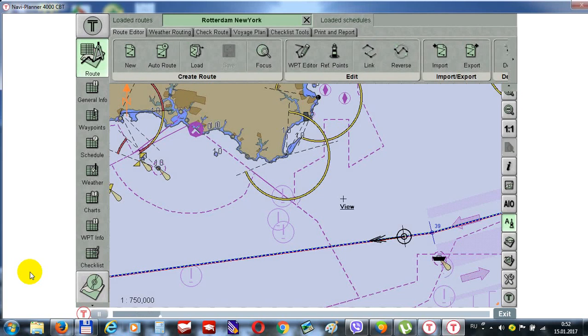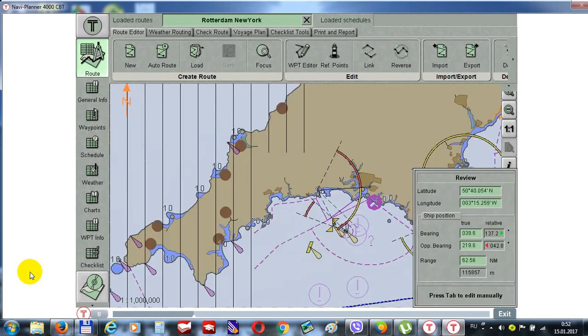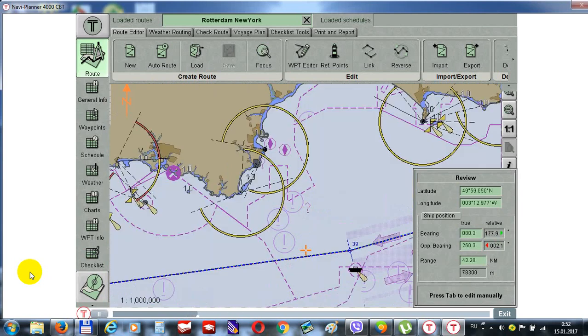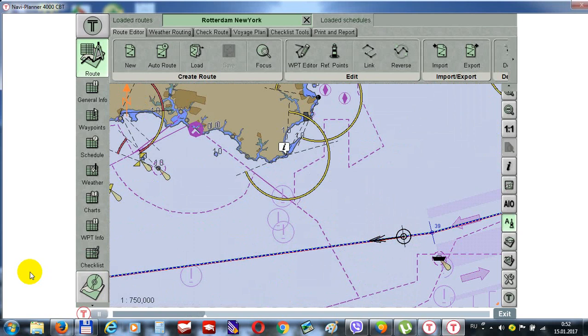The View cursor features additional capabilities. If the left trackball button is pressed, Review function is turned on, and the cursor acquires the form of a graphics cursor. Depending on settings, the graphic cursor can be displayed in two forms, short cursor and long cursor. By moving the cursor with the trackball, charts can be viewed beyond the screen boundary. View cursor appearance when positioned on a lighthouse. Select the left trackball button to call the lighthouse data card.